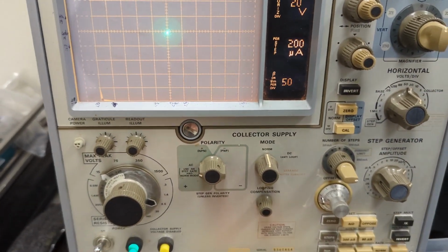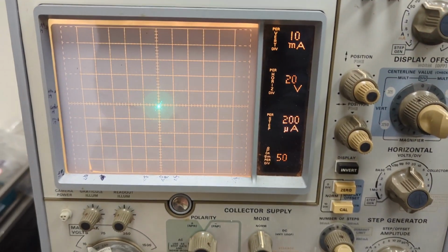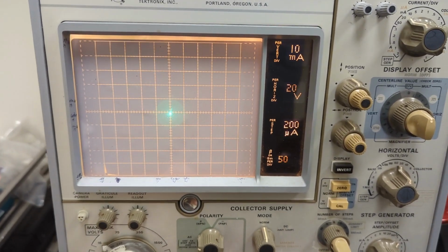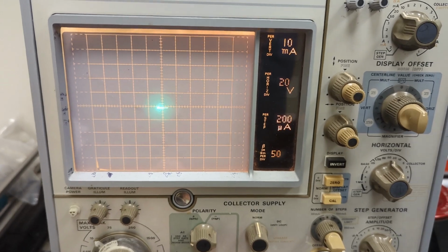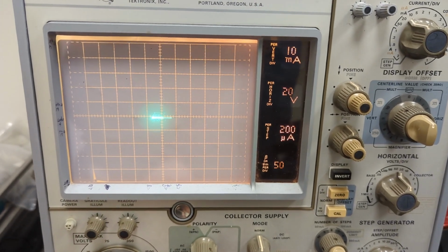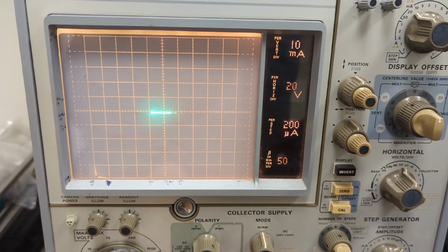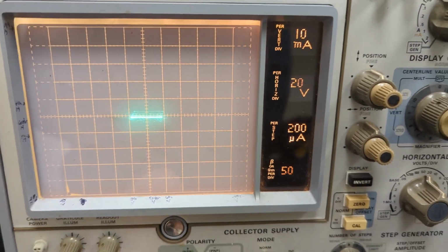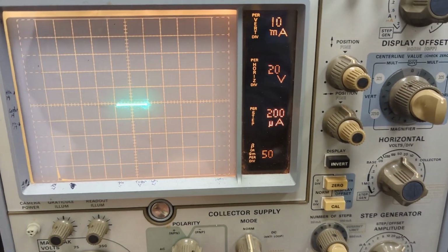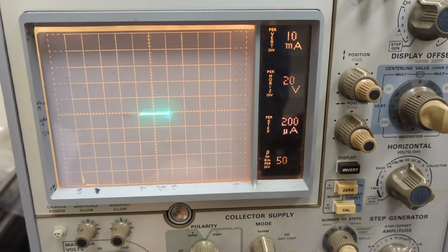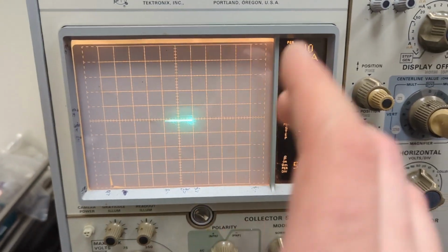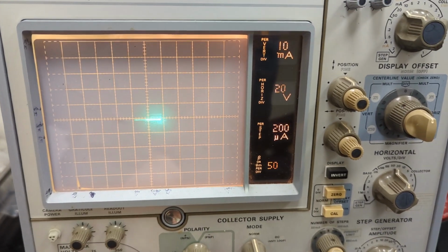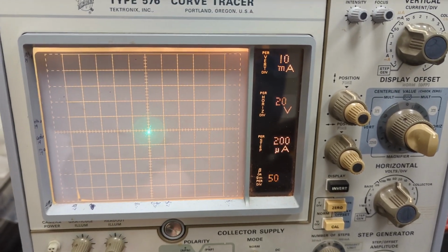I am in the low voltage mode, which can only provide a max voltage of roughly 15 to 20 volts, and I increased it to 9 and kept going. When I got to roughly 9, we did see the Zener breakdown, but immediately after that, it just completely died. And you can see now, this is what we're getting. So it's dead now.